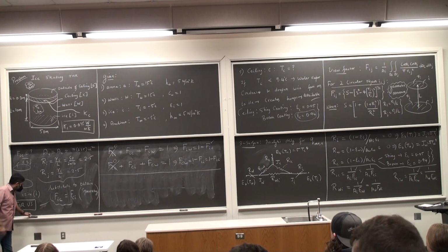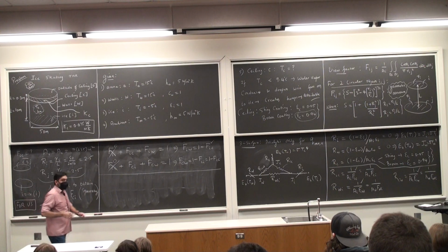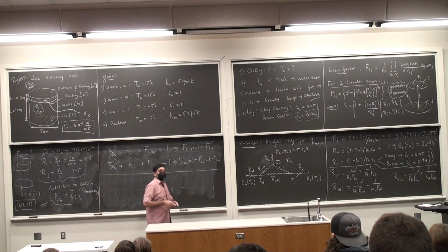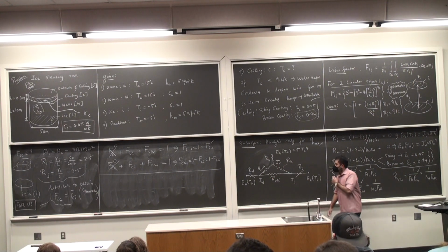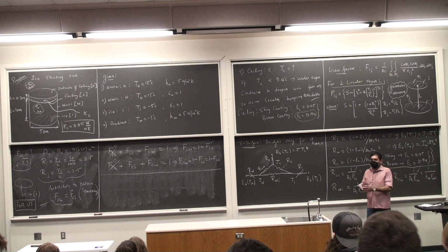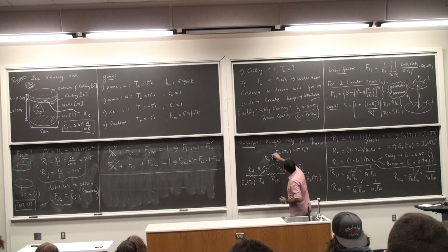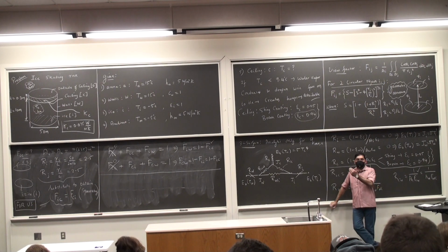What's our next step? I had what was called equation 3. You can see the ghost of that written here. I need to calculate Q radiation C as well using this network. So how to do that is by doing the following. What is Q radiation C here? Q radiation C is nothing but the heat rate that is flowing through from EB at TC.